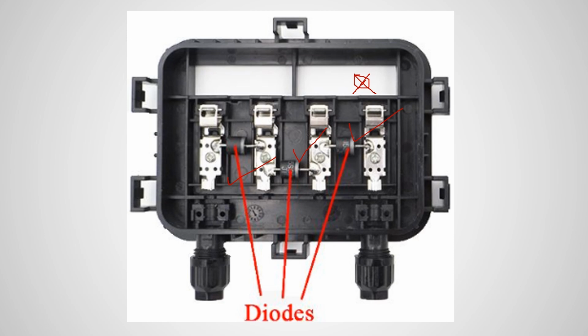So actually these 3 bypass diodes are dividing the panel into 3 sections and protecting 2 sections when one section gets shaded. Okay, so it means you have a solar panel divided into 3 sections and connected with bypass diodes. So what is the function of the bypass diode here? This bypass diode protects 2 sections from the other one which is shaded. Usually shading happens in one or a few cells, so that is the reason we are using the bypass diode.